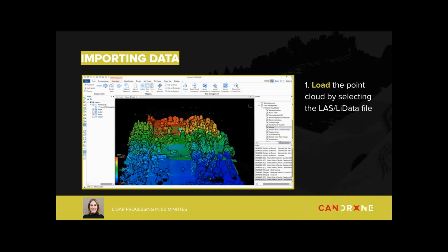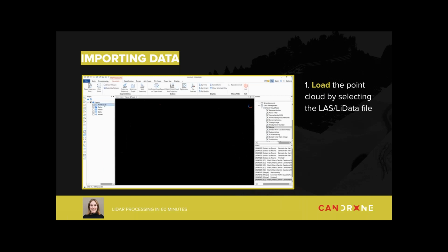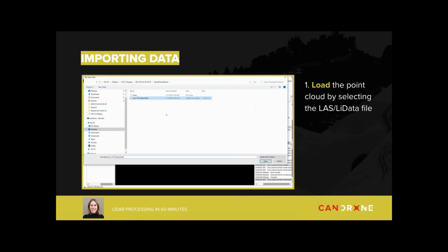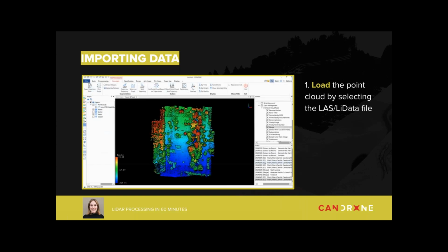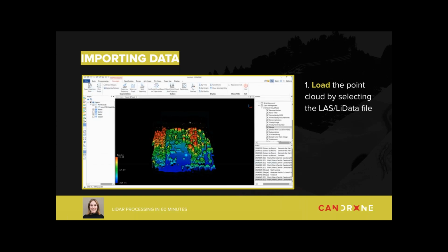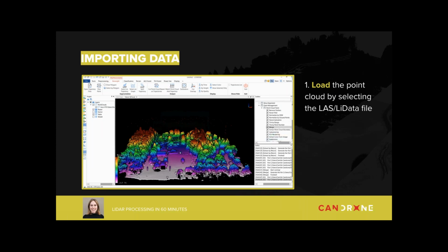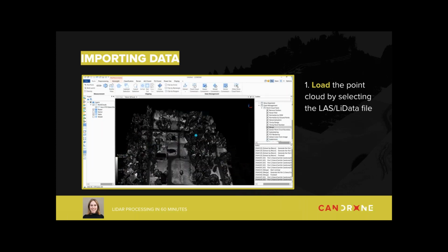And now to do this Boresight correction that I've been mentioning, we need two things. So first, of course, we need the point cloud, which we have hopefully just imported. And then secondly, we need a POS file, which contains all of the trajectory information from the drone flight.